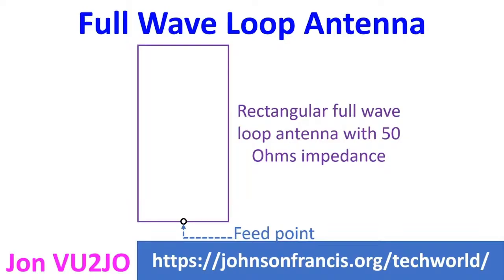A triangular full-wave loop antenna is another form of a vertical loop which requires only one elevated support. In a special case of full-wave loop antenna, a rectangle which is twice as high as its width gives a better gain and can match 50 ohms directly if used as a single element. Different shapes of loop antennas will have different gains and impedances. Gain and impedance also changes with the location of the feed point on the loop.